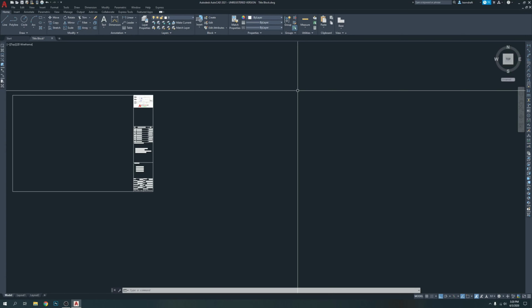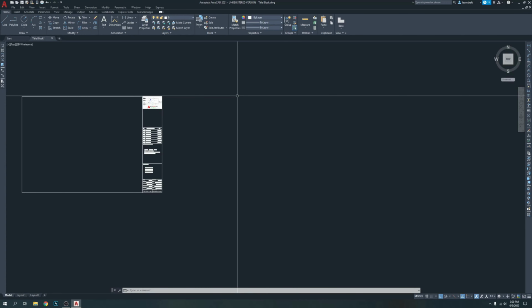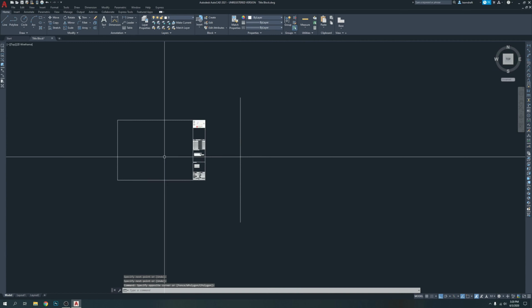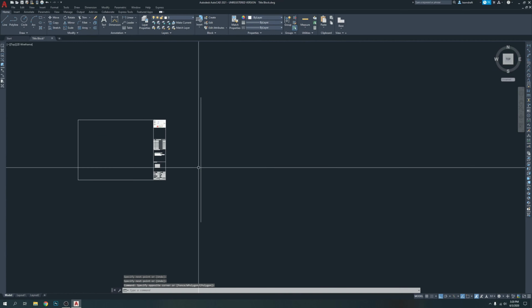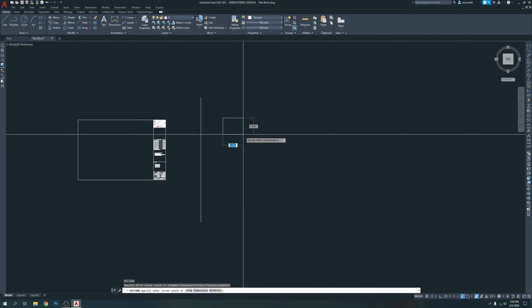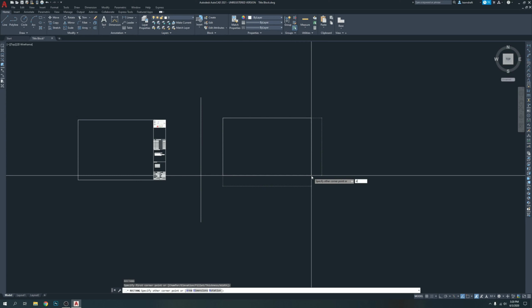So let's do it. Now I just want to make a separation, so make a line here, so we know we're going to work here, and this is just an example part. So let's create REC. I'm creating a rectangle. Enter, click D, enter, dimension 36, enter, 24, enter, click.